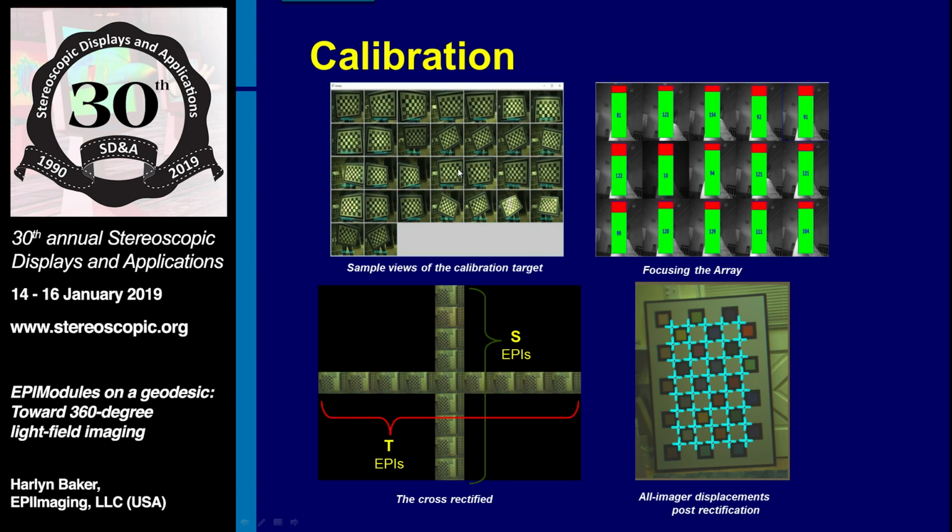We focus by running them at sort of reduced frame rate, so we can reduce the size so we get higher frame rate coming out of it. It's currently about 1 hertz over Ethernet, which is great. We have a Thunderbolt 3 implementation, but it's not quite ready to be used. So we watch the cameras as they're looking at a pattern, and we plot the sort of the gradient power. That's some of the squares of the gradients in the image. And in different windows, we can choose that, but here's over the whole image, where the green shows the current power and the red is the best it's ever seen on that camera. So we just have to tweak these knobs till we get the green everywhere, and then that thing's in focus.